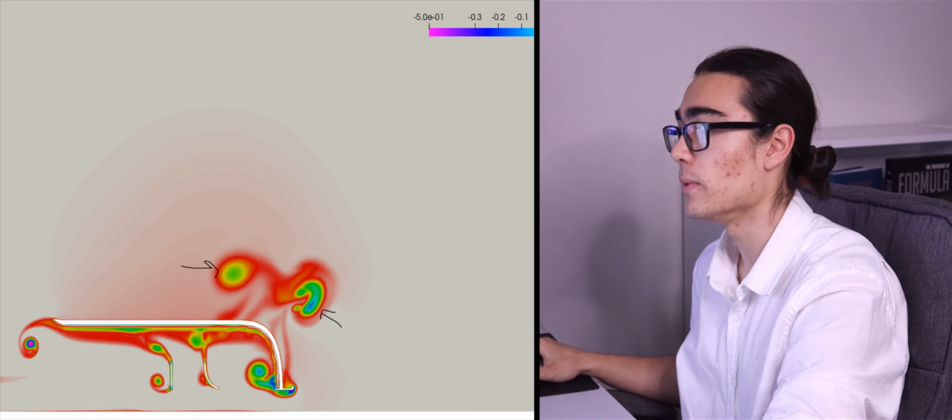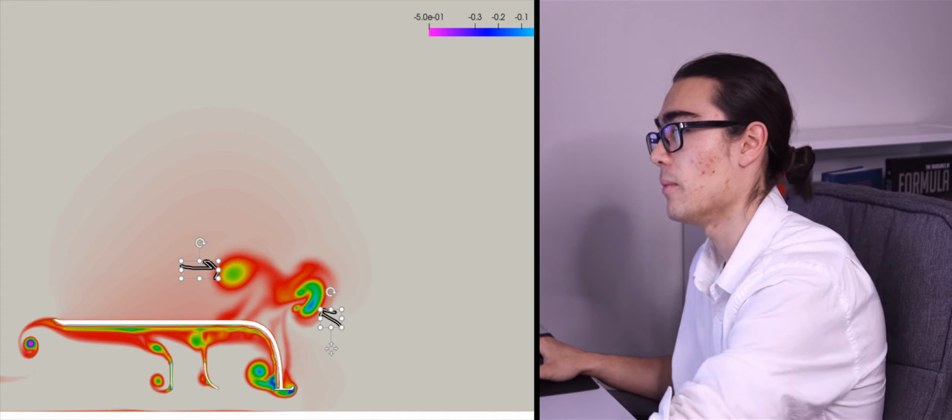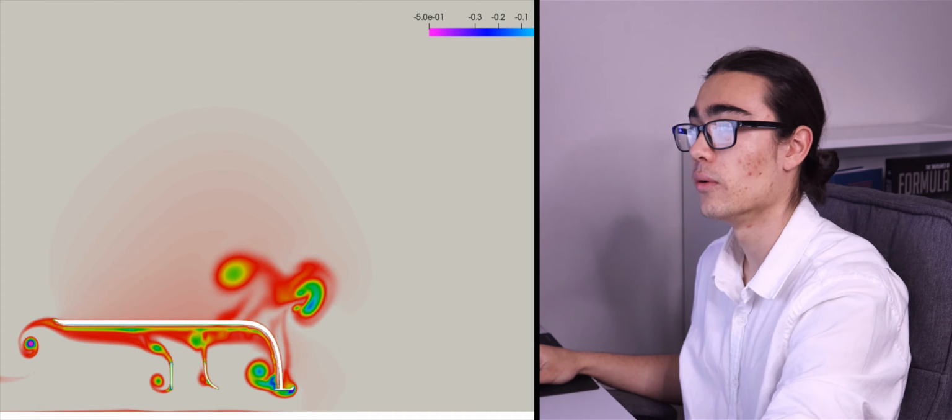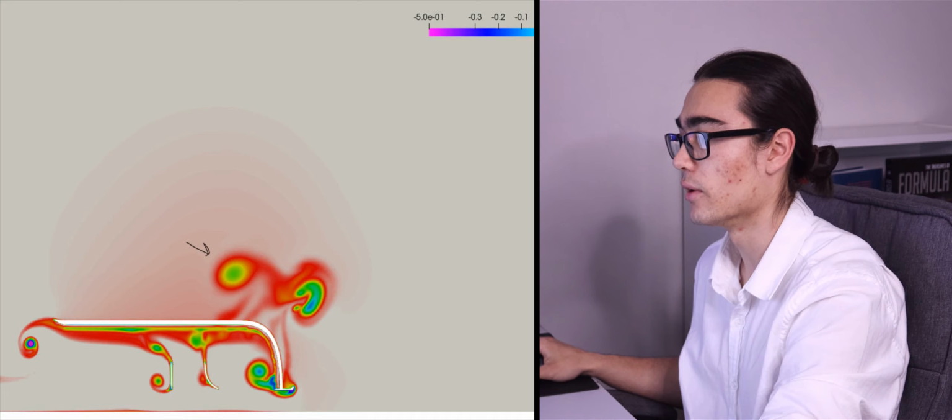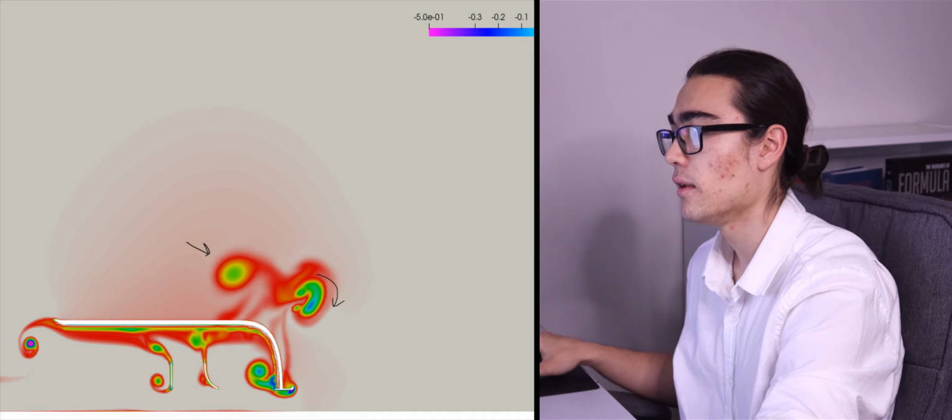So I'll be honest, I've always thought about our turning vanes on the front wing, so this structure that we create, and this one, the canard, I've always thought of them as two different structures. So the turning vanes, we can send them up onto the upper part of the tire, and I've heard from somebody I've talked to that you can actually churn up the boundary layer on the top of the tire and thereby reduce separation, so your wake is going to be better. So I kind of left it at that, and I was always just thinking about that.